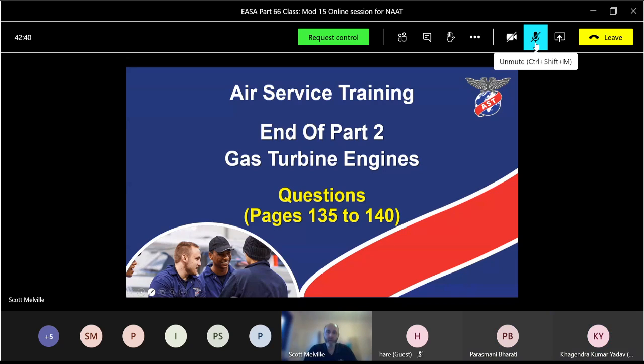What are the 4 thrust rating modes? Maximum takeoff, maximum continuous, climb, and maximum cruise. Good. What are the percentages for each of those? 100% of N1, 86 percent, 76 and 70% N1. Good man, thank you.